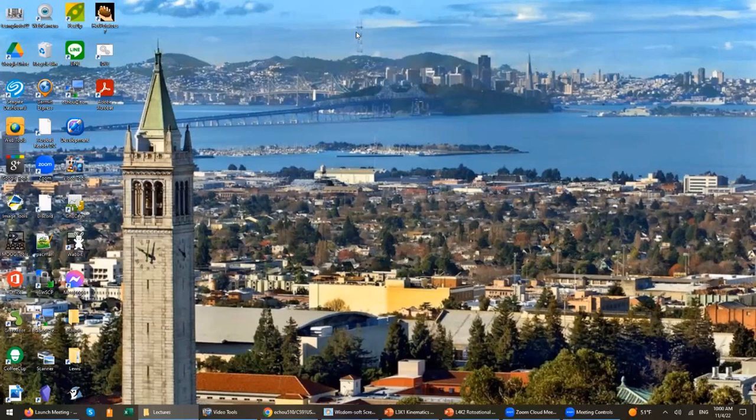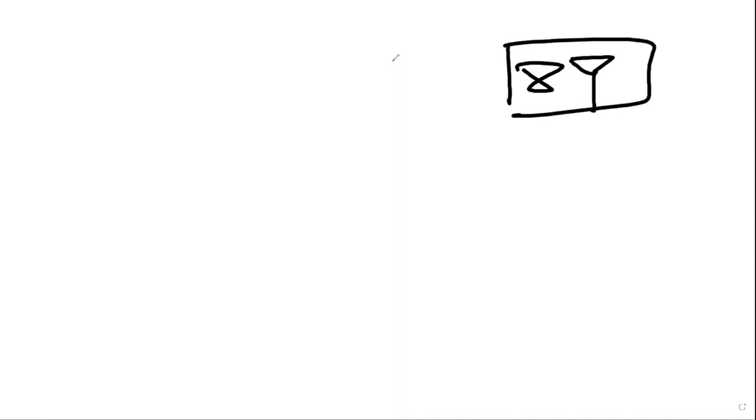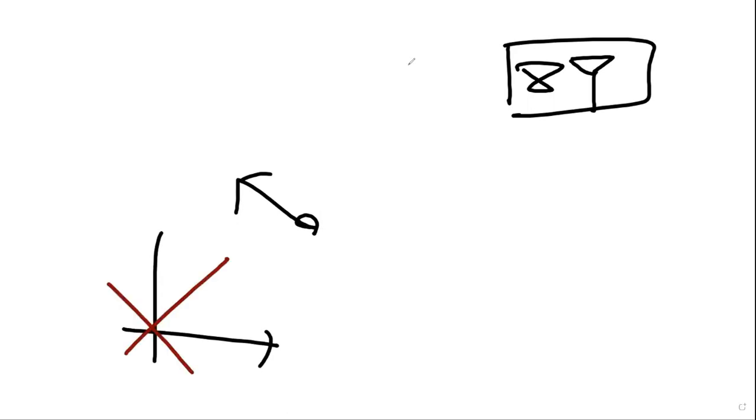And last time we talked about the big X, big Y method to calculate the coordinate after rotation and translation. We also discussed the relationship between the object motion and the coordinate rotation. Object motion is the reverse of the coordinate rotation. You just use a minus theta or minus displacement, and you will be able to get the right coordinate. That's the way we set up the calculation for the coordinates.